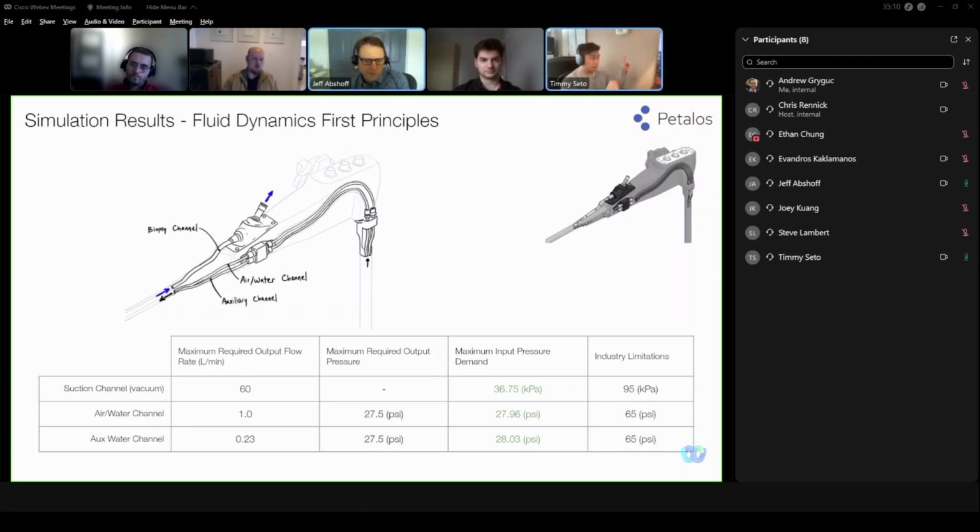The way we do that is it's essentially Teflon tubes that are overmolded with PU on top. So we're disregarding the effects of the PU because they don't really come in contact with the fluid, and we're taking all the material properties of standard Teflon tubing that you can buy from multiple vendors, and the lengths as well as all the fittings and their impact on the entire system. Okay. And so these output boundary conditions are at where you're indicating here, the arrow markers, or at the end of that long tube? At the end of the long tube. Okay.